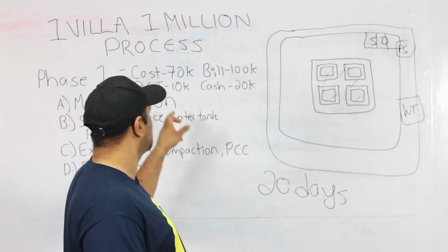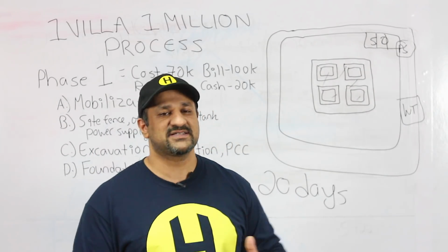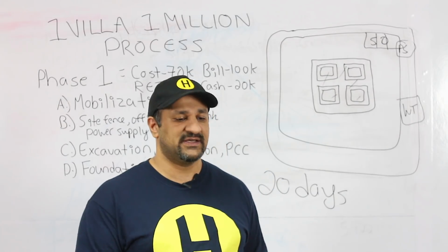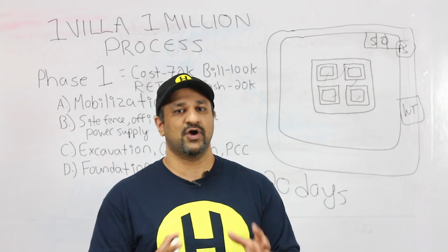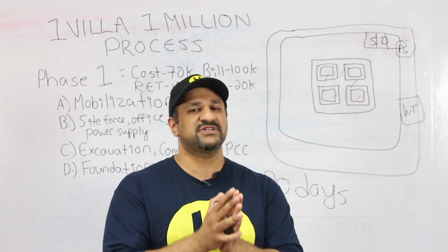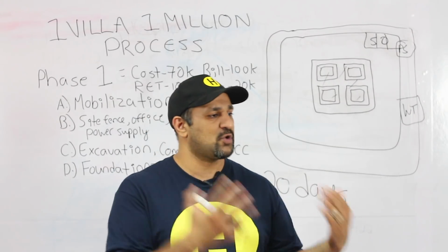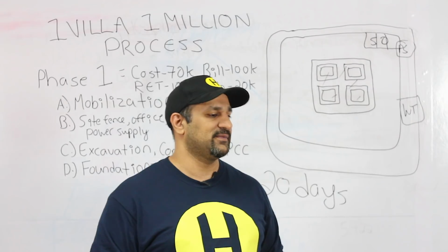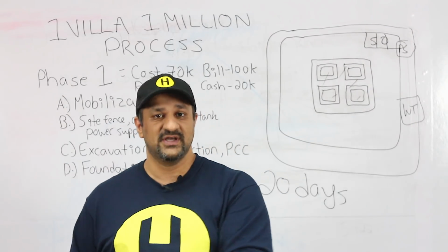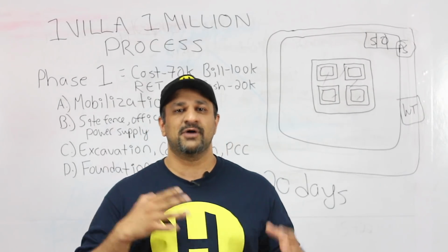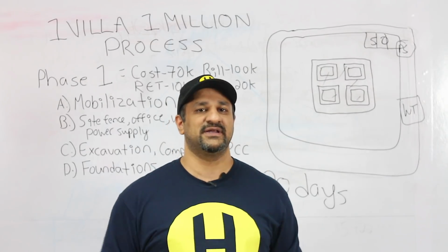Out of the 100,000, there's 10,000, which is 10% of every bill that is submitted, is kept for retention. Retention is basically kept on the side. So when the property is completed, when the whole construction work is finished, the retention is kept generally for 1 year. In case something goes wrong with the property, something goes wrong with the foundation, or the property is not done in a correct way, the retention is used in order to fix the property if there's anything. So this is almost like an insurance, almost like a guarantee that happens for around 1 year after the property is completed.